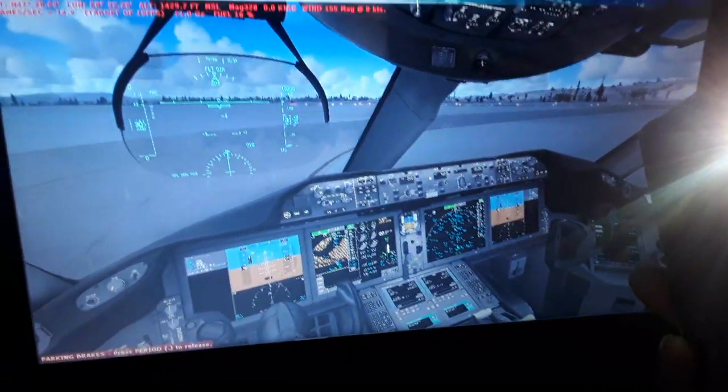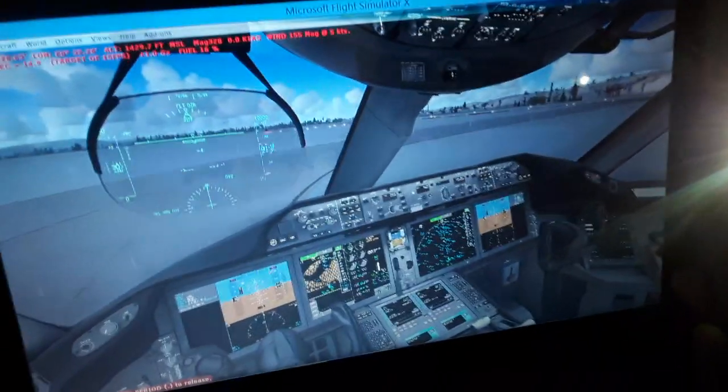We have also the vertical rate of climb and descent of the aircraft, or the VSI, vertical speed indicator. That displays how fast the aircraft climbs and descends. Also you can set the flight path angle in degrees in the autopilot flight director system panels, and the modes you can use. You can see also we have the HSI, the horizontal situation indicator, that displays the magnetic heading and track, and the standby, the degraded flight plan display.